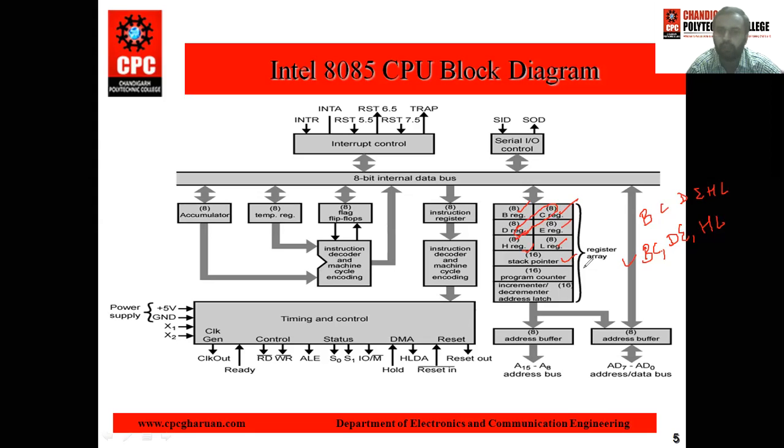Next is the stack pointer. The function of the stack pointer is to store the address of the top of the stack. As we know, the stack is a last in first out device, just like a tumbler as shown in the display. Suppose this is a tumbler and we add different balls named A ball, B ball, and C ball.